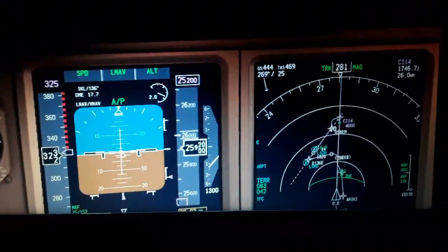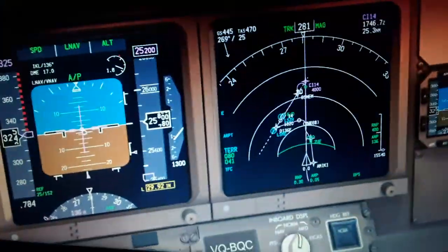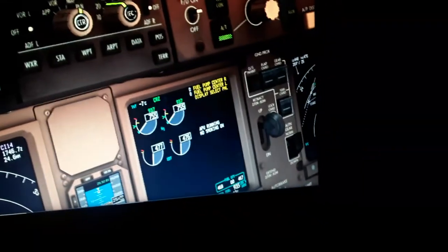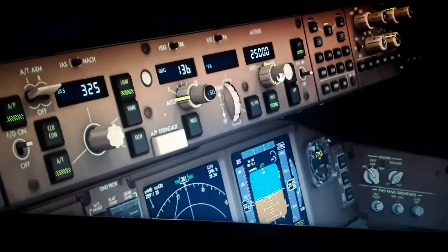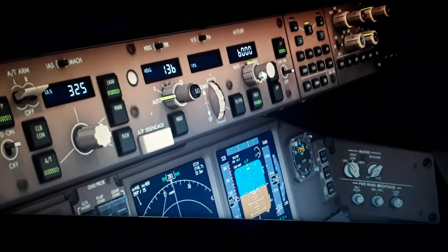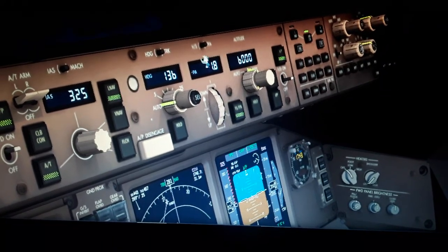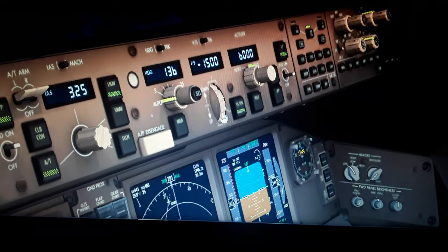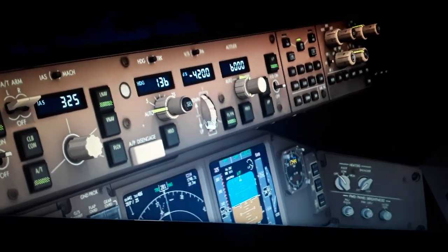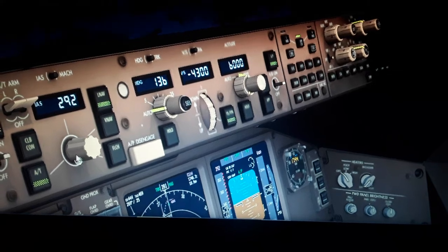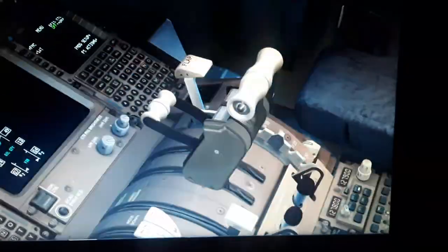to look around. Here we are flying almost level with the autopilot command. You can see the AT1. We need to start descent. We are just 34 nautical miles, so select a lower altitude now. Target altitude over here like 6,000 feet, and also VS, vertical rate of descent, and also a little bit less airspeed. So we need to extend the speed brakes now to slow us down, and also less airspeed.